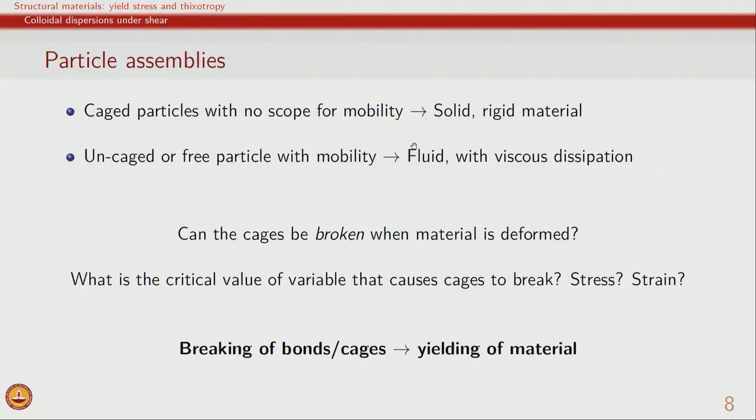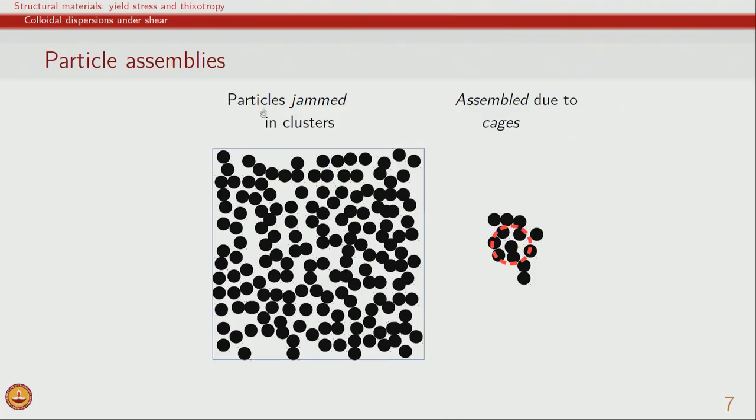And so, for such materials the jammed states are observed because the interparticle attraction is not a significant factor. The particles do not come together because there is an attraction between them; the particles come together because there is excessive population. The concentration of particles is so high that they are forming these cages, and because of the formation of the cages they do not allow motion for each other, and in that case they are jammed.